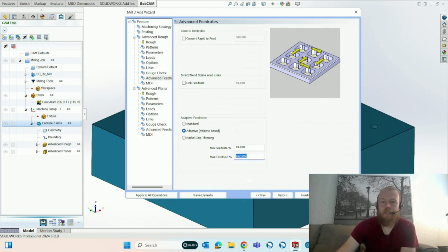For example, when the tool is getting into larger material at a time, like into these corners where my cursor is located right here, if the tool is getting into larger material at a time per tooth of the tool, the software will calculate how slow the tool needs to move to keep a constant chip load, and that can reduce chattering at the machine.